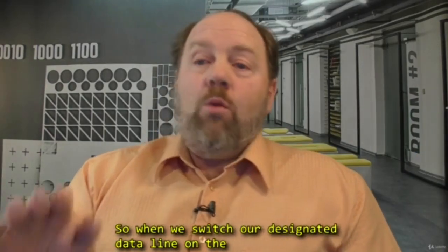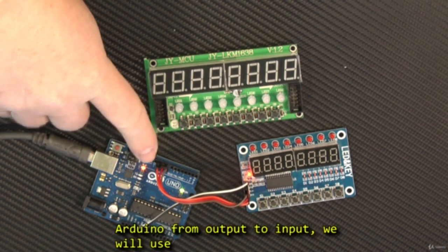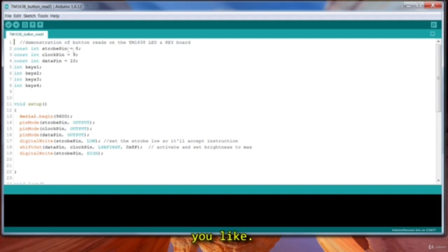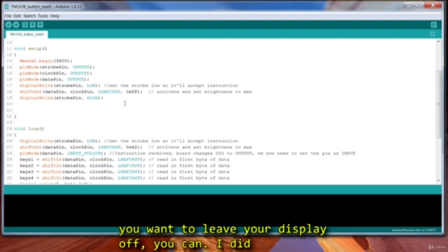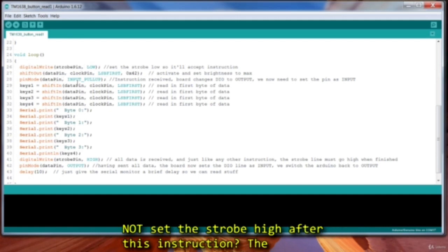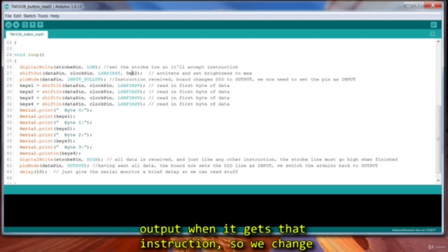Perfect. So when we switch our designated data line on the Arduino from output to input, we will use the input pull-up instruction. Now, I have sample code in the download section if you like. We set up everything the way we did before, and if you want to leave your display off, you can. I did, but it doesn't matter. We then set the strobe to low to send an instruction, which is hex 42. Notice we do not set the strobe line high after this instruction. The controller immediately switches the DIO line to output when it gets that instruction.